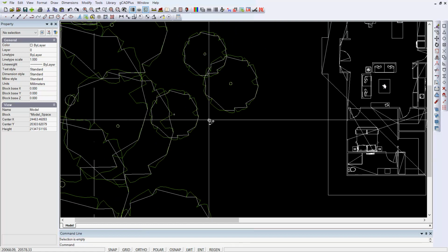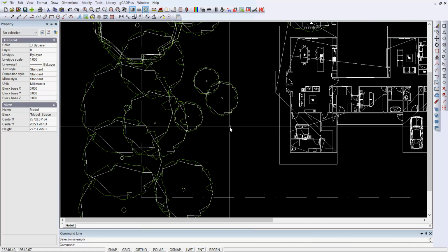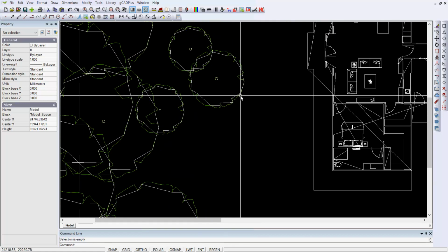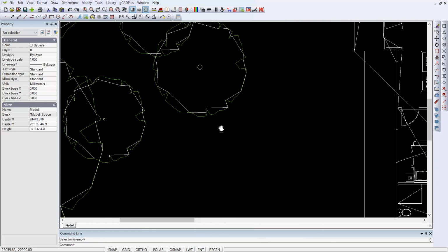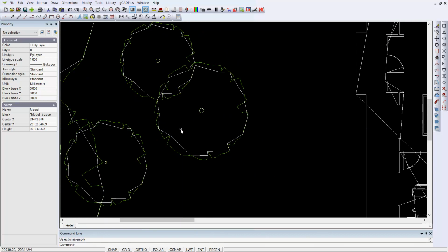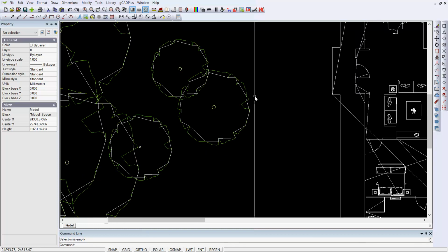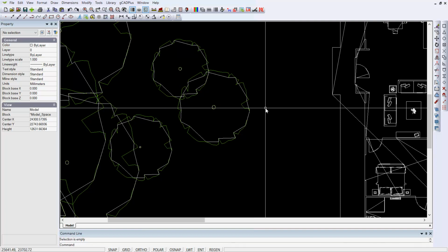There are thousands and thousands of individual entities in here, and I'd certainly be inclined to take some of those and replace those symbols with one of our own and then eliminate those. It's tedious, but you'll get a much better result and a much cleaner and much smaller file. However, I think this is workable for the particular job.